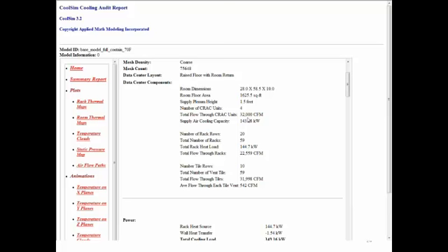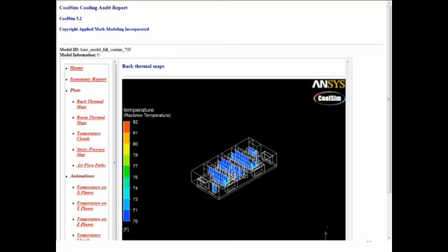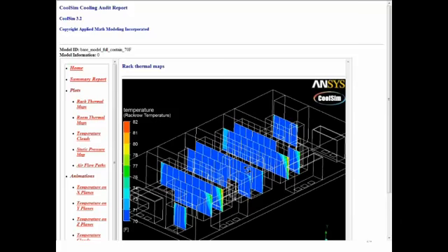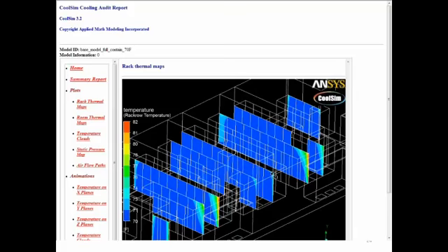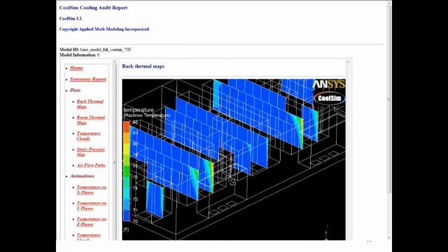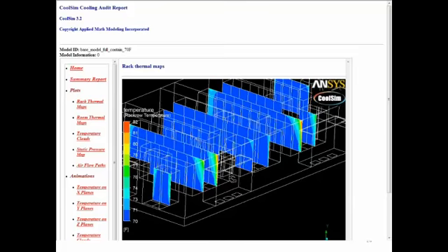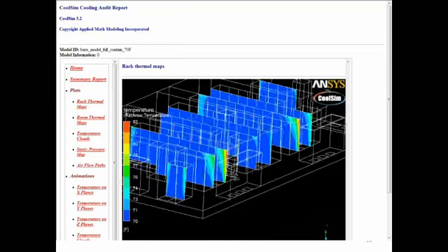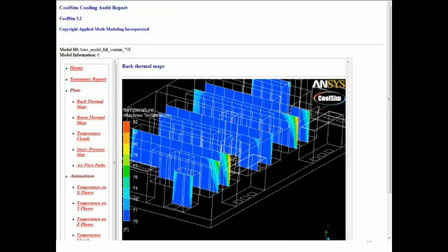Yep. So this is the case, Liz, that is running at 20% down or 80% of max. I've got my RTIs there. And if you take a look at the thermal maps on this, they're nice and uniform. They look quite good. Typical of any contained case. That's right. Now you see there is a corner right there that's a little bit warm. That could be that I didn't have my containment absolutely tight, which is actually a pretty fair representation of the real world. Right. The other point about it, Liz, is it's right on an edge anyway.